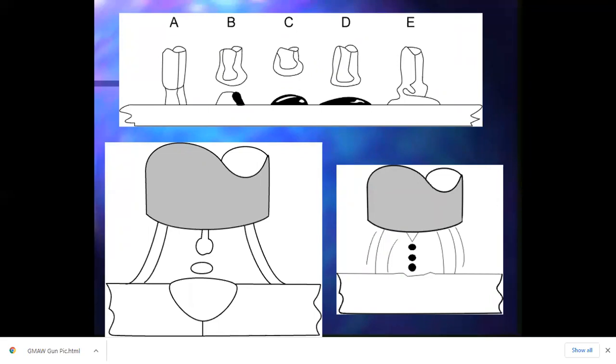But got some examples up here. So this is an animation of short circuit because what we have is the steel coming down, being pinched off, basically retracting, coming down, forming short circuiting in the puddle again. This one on the left here on the bottom is going to be globular transfer. We see that bigger dot of steel coming across the arc. And on the right is our spray transfer. These are just rough animations, give you an idea of the processes. Obviously not to scale, but quite neat. And as long as you know how to use them and how to properly work with these different modes of transfer, they'll be awesome. They're great.